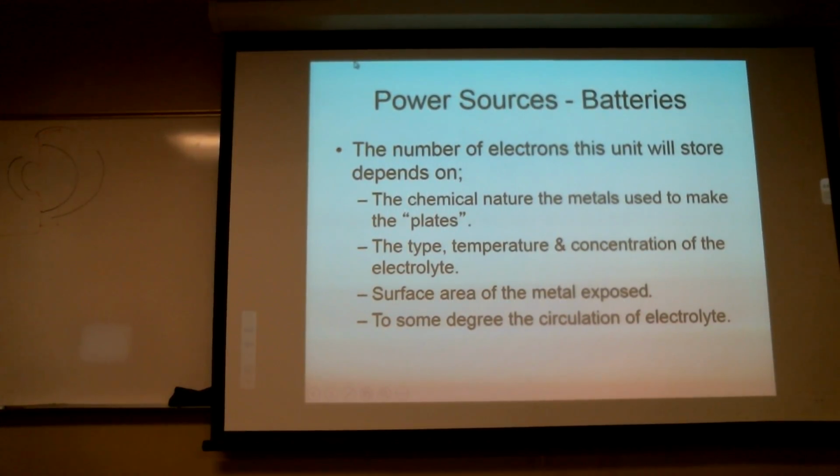Okay? So I don't know if they covered the galvanic chart in general when they were talking about corrosion? Yeah. So if you look at the galvanic chart, there's, I forget what the metals are, but there's a long list of them. And regardless of where you are in the chart, the further away you get, the more corrosive it is, right? Well, that's also true, the further apart you get, the more voltage potential exists between the two, okay?